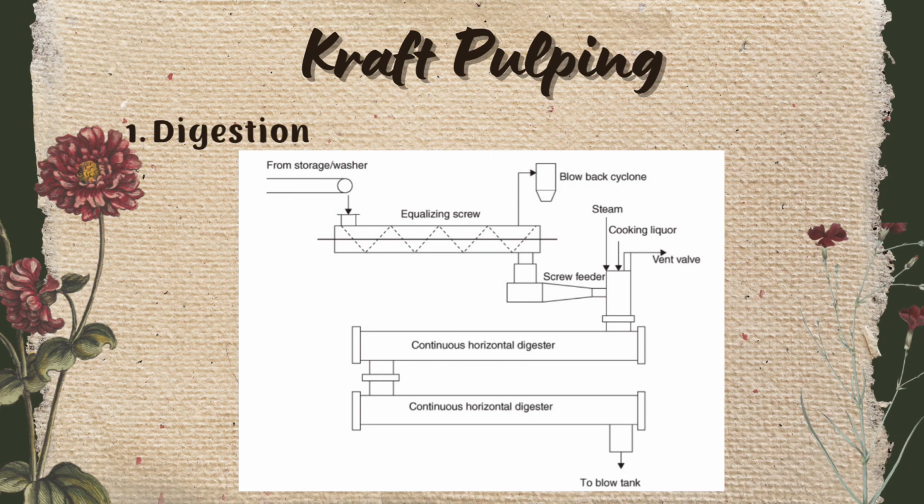The wet bagasse is conveyed from the stockpile over a metering system and fed to the screw feeder. This removes excess water and creates a plug of bagasse which allows feeding of the bagasse into the pressurized reactor. Steam and cooking liquor are subsequently injected. A blowback valve may be installed on the inlet chamber when inadequate bagasse is metered to the digester.